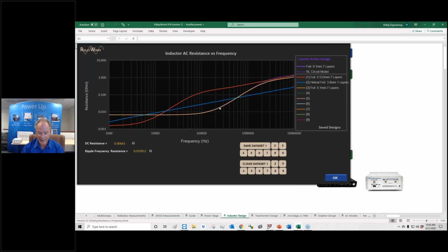So now you've got to think again. You can't take these nice flat wire inductors and put them in an LLC converter. I'm sure the magnetics companies already know that, but I don't see too many doing the flat foil design and then a very thin design. Because we're not filling out the window, of course, now we can actually shrink down the size of the inductor. So this is just another example of every topology playing this differently. And your job is generating these different curves and learning how to massage them around.